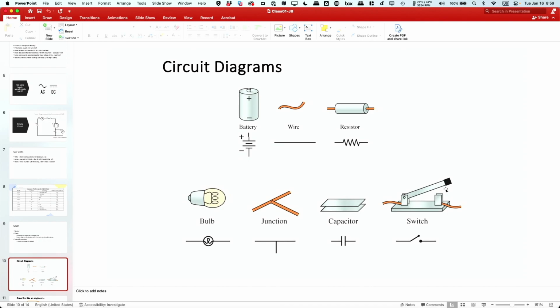And this is then nominally DC. Basically what happens is that single diode lets each forward going pulse through, and it charges up the capacitor. While the AC is in the wrong direction, you're running your device off the capacitor, and then it recharges the capacitor on the next pulse.